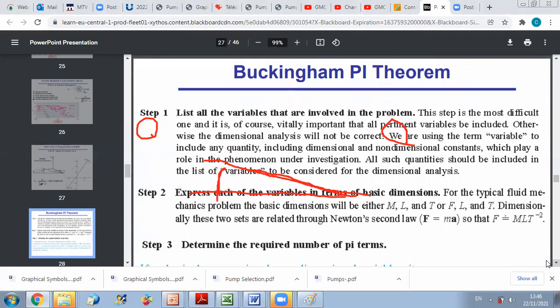Now the next step will be how to determine, in a certain problem, what the dimensionless numbers of interest are, and then to proceed to experiments. For example, in the example of the cylinder, we said that the main dimensionless numbers were CD, CL, L over D, epsilon over D, and Reynolds. And then we should do experiments to construct graphs.